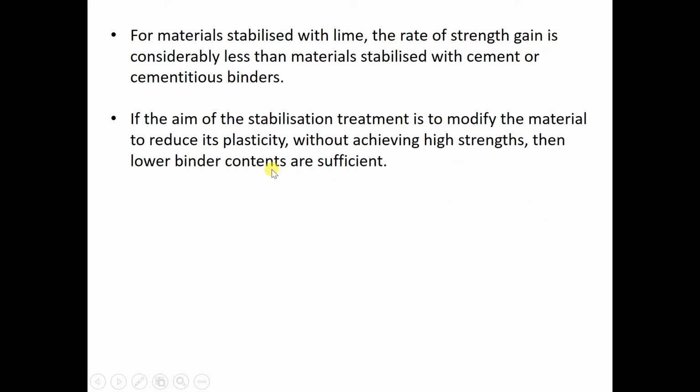So you could use a lower binder content of lime. We don't need to use a lot of lime, unless you really want the strength increase, then you probably have to use more lime.